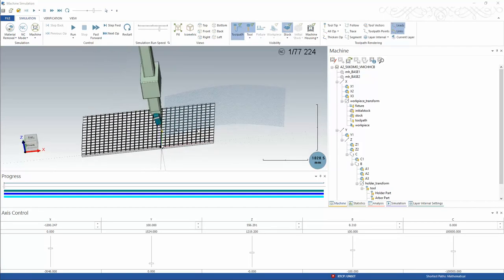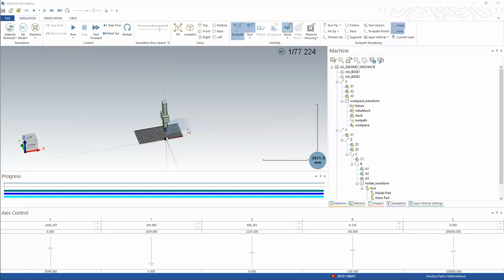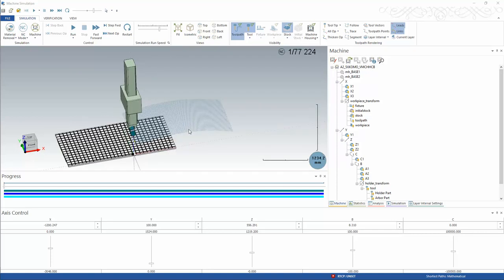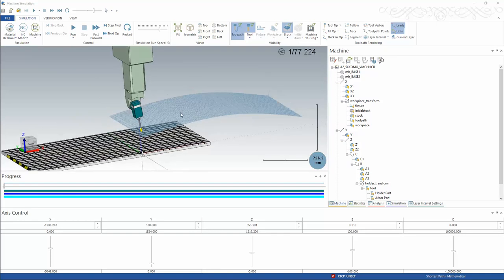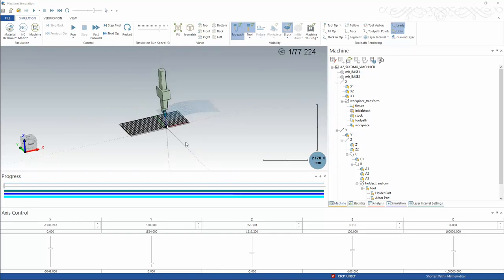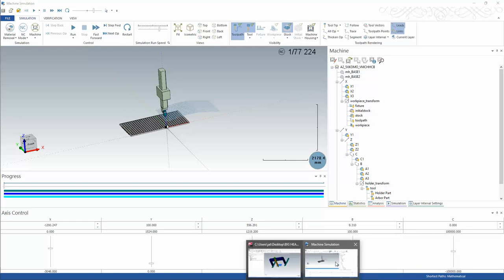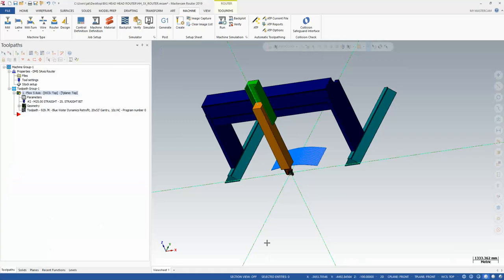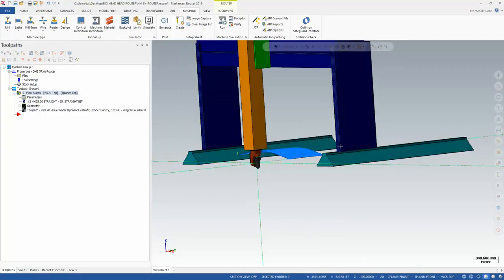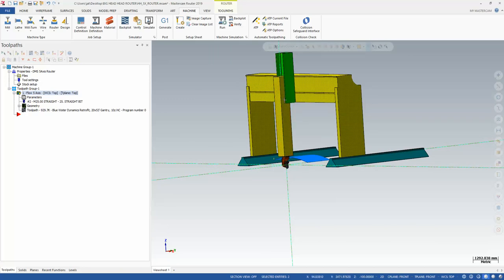All right. And just to point this out, I'm not going to go through the details of the machine sim here. I went through those details in another video that's on here that went fully in depth on how to save off the STLs and all that stuff. So I'm not going to go into that much detail, but I'm going to quickly go through and show you what's involved in building the machine sim. So to do that, this is the standard 5-axis head machine, and let's go off and save these files off of this machine. Obviously, this machine is super simplified, but the basics to build the machine are all there.